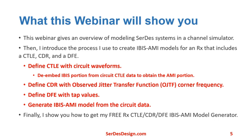Include the ability to de-embed the IBIS portion from the CTLE circuit data to derive the AMI CTLE portion, and generate an independent standalone IBIS-AMI model from the data. Finally, I show you how you can get a copy of my free IBIS-AMI model generator for a receiver with CTLE, CDR, and DFE for use with any channel simulator.